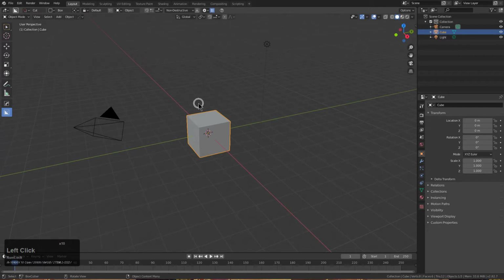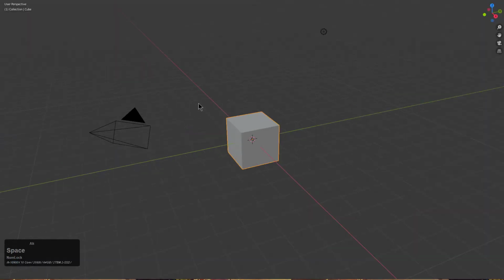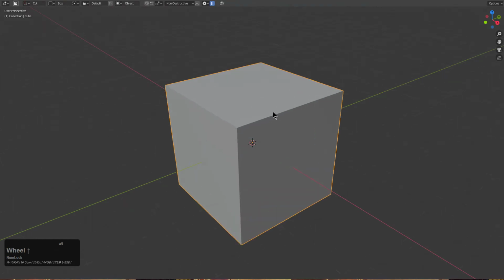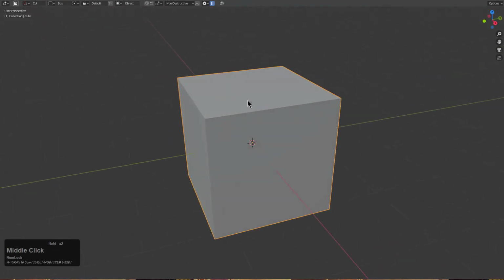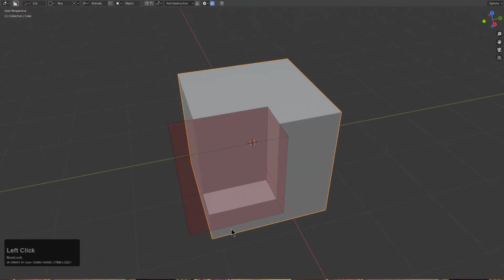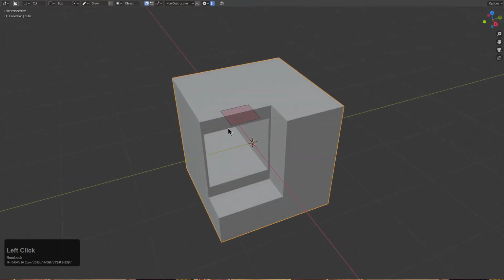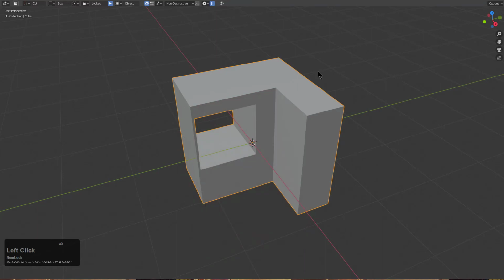So I'll press Control Alt Spacebar in order to maximize our view, which also gets rid of the top bar. So I'll press Alt W to show up my top bar, and now we're ready to rock. So for the most part, BoxCutter hasn't changed. You should just be able to get in here, draw, turn on snapping, use your snap dots to draw and cut through things. However, with the addition of release lock, things definitely change and get more interesting, because now